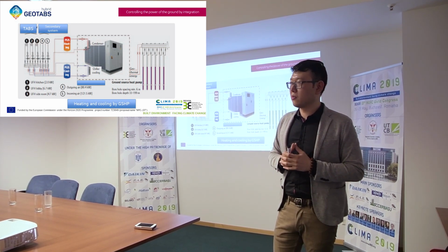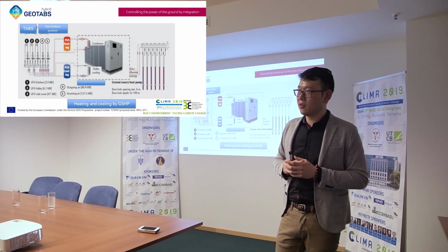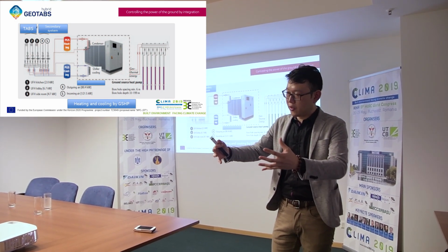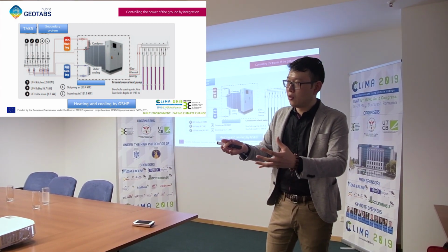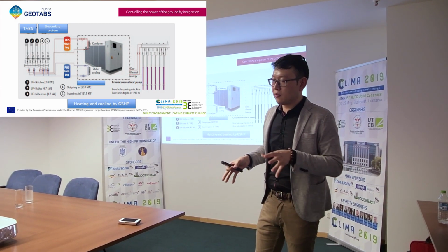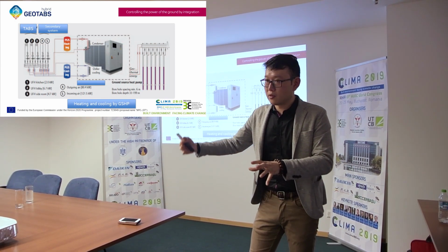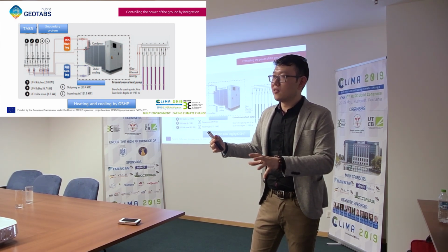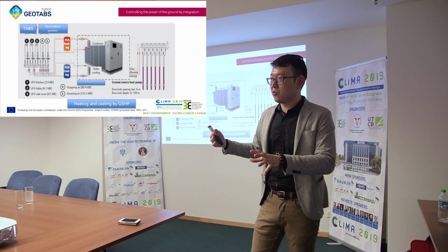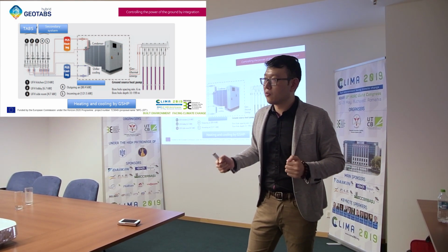I think Pieter showed the picture before. Usually you use mixed valves. So you give the same water, and if it's needed for the peak load or secondary system, you lift it up. Or you have two separate systems. The supply temperature is always the same to the taps, but you can vary it to the secondary system. But then, when you have a complicated system, the control comes to your mind. Because if you don't control it, it will become like a baby, and you never know how it will react.